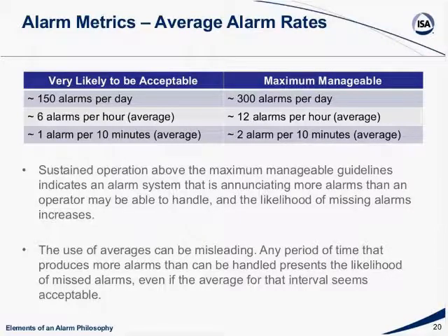You want to really engineer the system, though, so that when you do have a process upset, you don't get more than 10 alarms in 10 minutes, because if you go beyond that, you have an alarm flood and the system becomes unmanageable. An experienced operator can handle these things pretty well. They've been through it before, but newer operators or board operators haven't seen a lot of these scenarios come up, and it makes it very difficult for them to get the system back to where it needs to be.